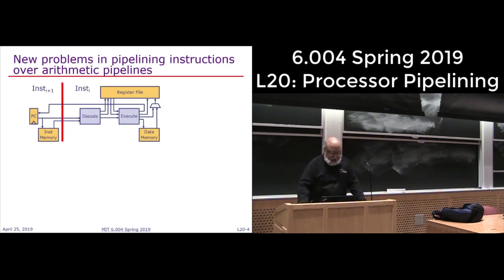All right. So what are the new problems that arise in pipelining? And the first one is the one that surprises everyone. So I have given you a pipeline where I've just drawn a two-stage pipeline. You do a fetch and then the rest, whatever. Sometimes it takes 1 cycle, sometimes it takes 2 cycles, this right-hand side of it. But notice what will happen. Suppose the execute side is executing instruction I.